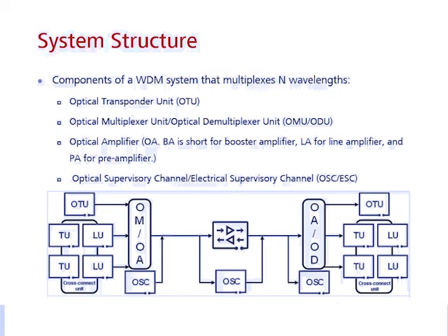Okay, then after long distance transmission, your power will be decreased, right? But we need to make your power higher again, because we want very, very long distance transmission. If the power is already too low, we cannot arrive at the next station. So in the middle of your network, you may need another unit, that is the regenerator unit. Okay, actually in the transmission network, we have two different regenerator solutions. The first one is the electrical regenerator, which is widely used in transmission networks. This electrical regenerator is very good,